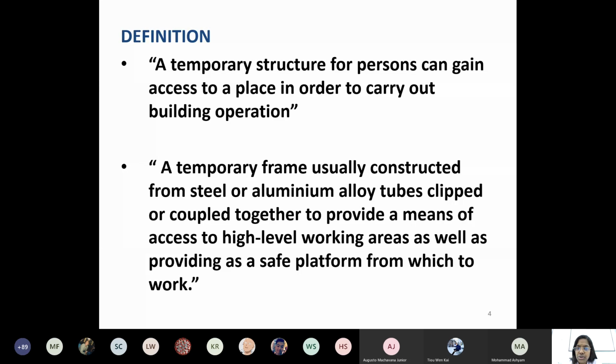Okay. So far we have studied only the formwork, the boxes that are the temporary structures used for making your concrete in situ. Now we are going to see how this formwork is supported at some height, not at lower ground. Any elements that are constructed more than 1.5 meter high have to be supported safely so that people can go in, prepare it, pour the concrete, or prepare the reinforcement, everything done on the site.